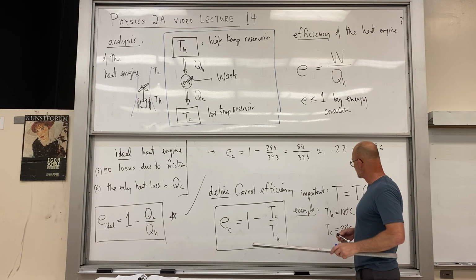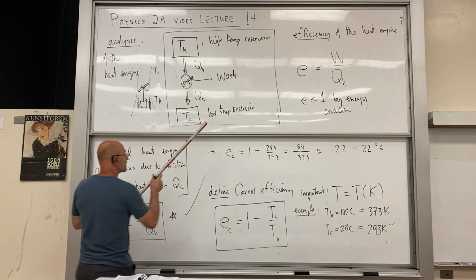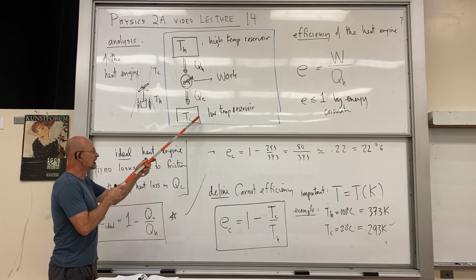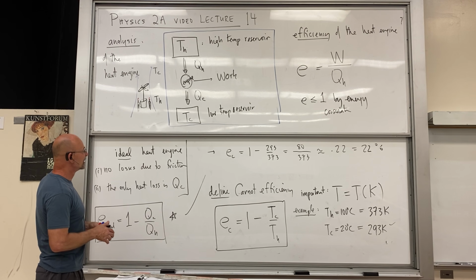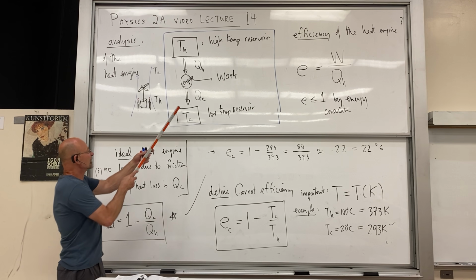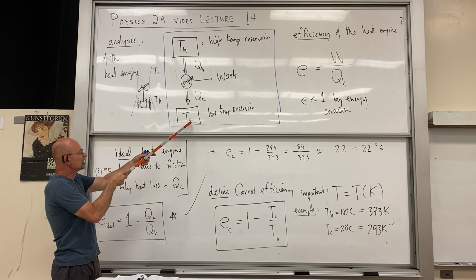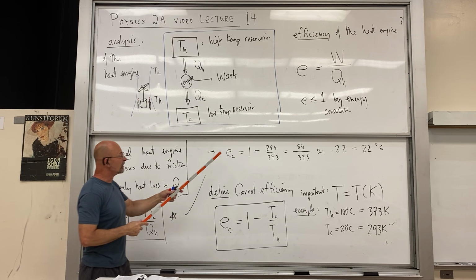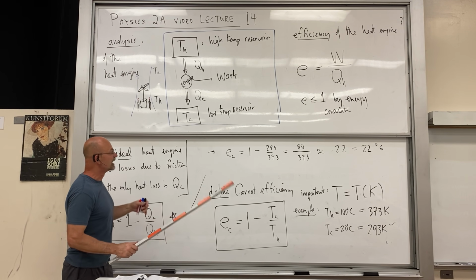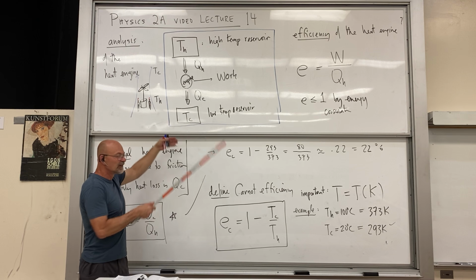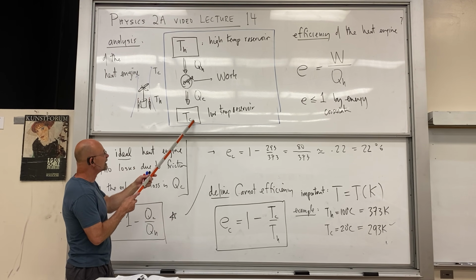Now here's a couple of other points. One can go on and on with this. This low temperature, even if it's just room temperature, it is not a given, because you're exhausting the heat to the environment, and what can happen is you're unable to exhaust it rapidly enough, and in that case, your engine's actually going to build up heat.